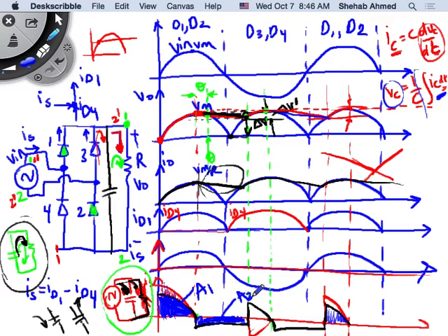A2 in steady state. And initially, forget about this. Initially, I drew this a little bit bigger than these. I do this first black one. I drew it a bit bigger than the other two black ones because initially the capacitor was not charged. But in steady state, these black waveforms will all have the same height and they will have the same areas underneath them, right? So A1, the area under the curve for a capacitor, A1, A2, A3, A4, all of these areas have to be equal in steady state. Okay, so forget about the initial transient, but steady state, they all have to be equal. Good point.